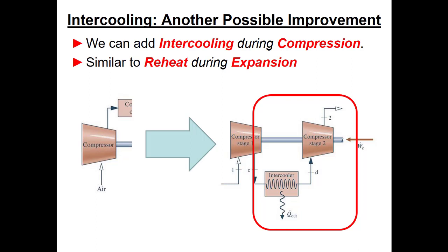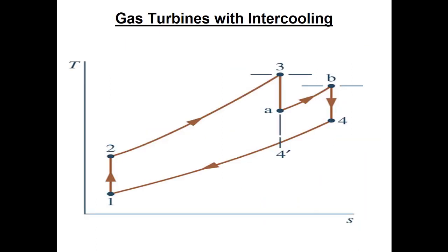Now, we never did this in Rankine cycles because it didn't take that much work to increase the pressure of that liquid. But remember, we talked about how the backwork ratios in these natural gas power plants are typically much higher than what you'd see in a Rankine cycle. So now we're going to use this strategy as well to improve our net work by reducing the power required to compress the gas up to the pressure that we want.